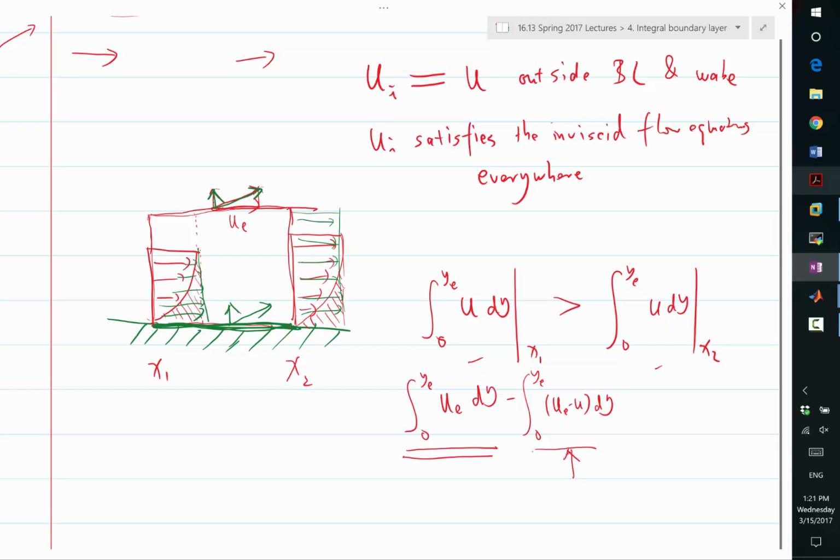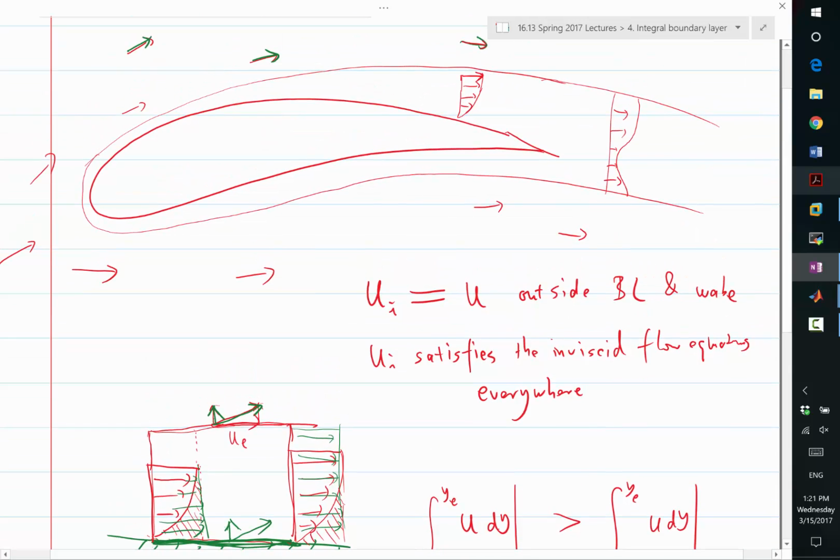All right. So this is the inviscid equivalent flow. So basically, the velocity here is an extrapolation of outside velocity, in the sense that because the velocity profile here is not exactly tangential to the wall, is not exactly parallel to the wall, the velocity at the wall can also not be parallel to the wall. So the velocity profile is like that.